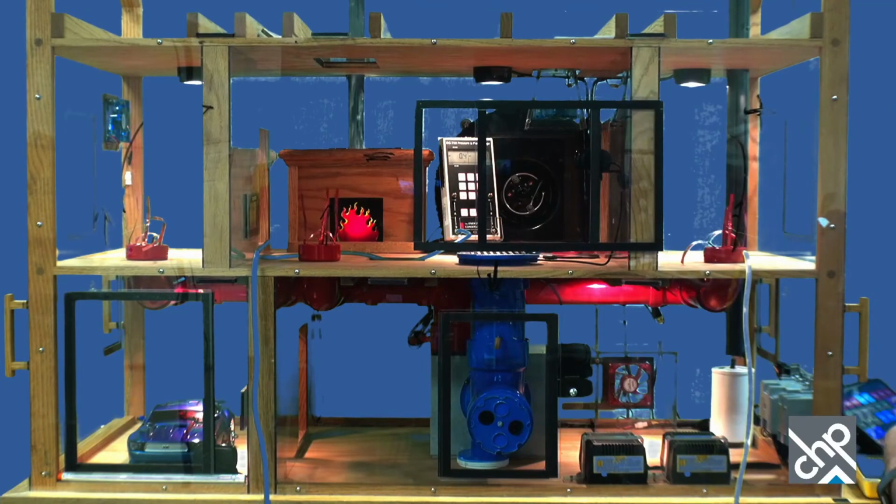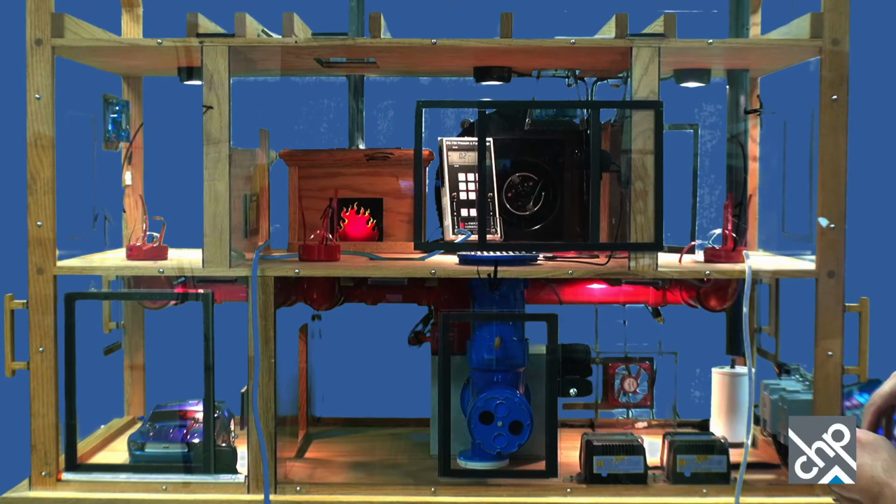So I'm going to open this door back up too, and then we're going to switch over to the bedroom there for a second. I'm going to turn my fireplace off. But what I want to do is switch over to the master bathroom, and I'm going to show you measuring the room pressure. And room pressures, you can measure those by putting a hose under the door and measuring it back to what I call the main body, where the hallway, central area of the house is. And that's the way I've typically done it over the years.